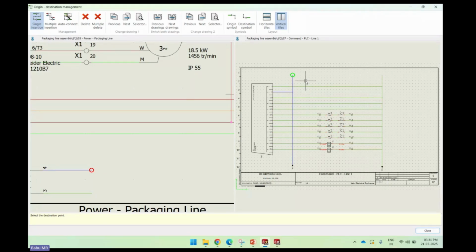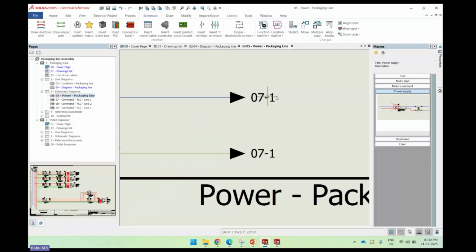Okay, it will select the same wire, and it will not allow you to connect with a different equipotential wire. I can select the same wire, and it will completely reduce your errors. Here I can use the control draw wire, select the same wire, and it will create the arrow showing where it is going.